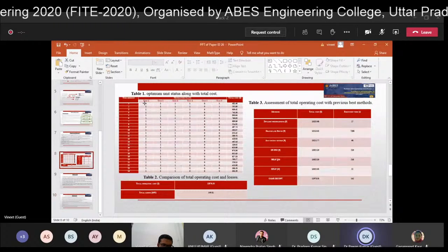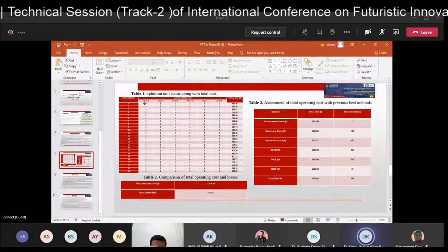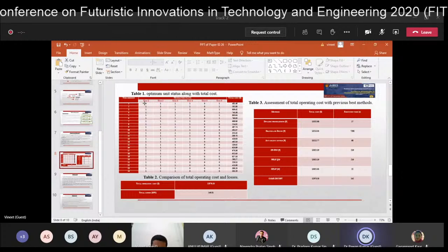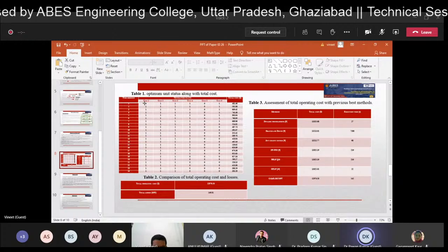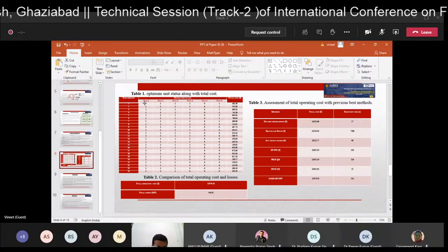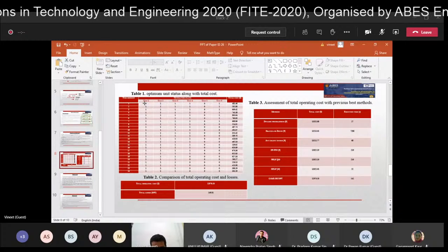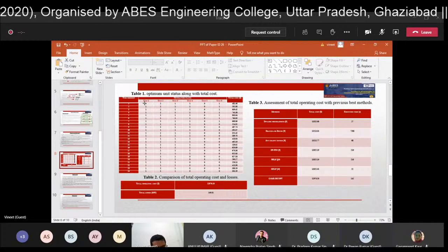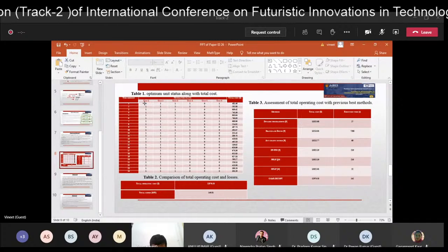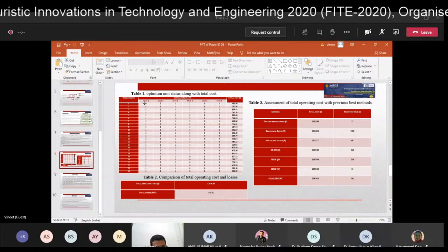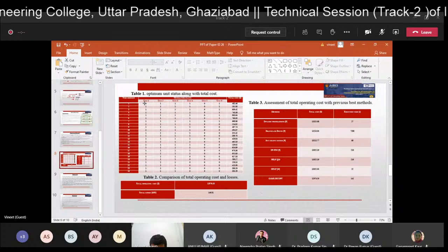If you have 6 generating units and we want to operate our system in economic load dispatch, but at the same time we are implementing unit commitment, can you differentiate the two? Yes, sir. Actually, in economic dispatch, there is a certain number of generating units, and we have to satisfy the total demand. But in the unit commitment problem, there is a certain number of generators, we have to satisfy the demand, but also decide which is the most efficient unit, and for how much time period it will run. Suppose there are 6 generating units. Now, in these 6 generating units, which is the most efficient unit?